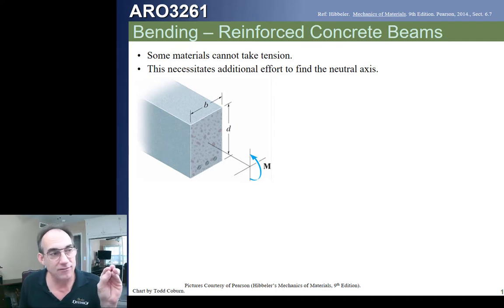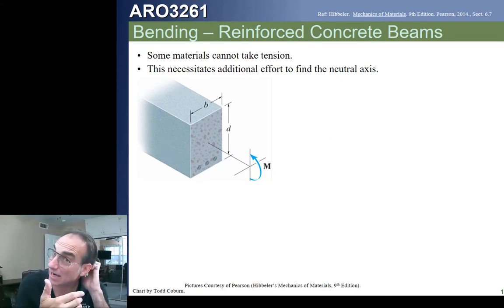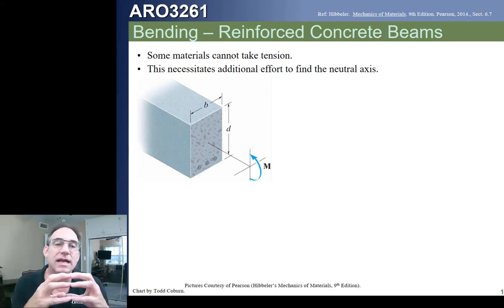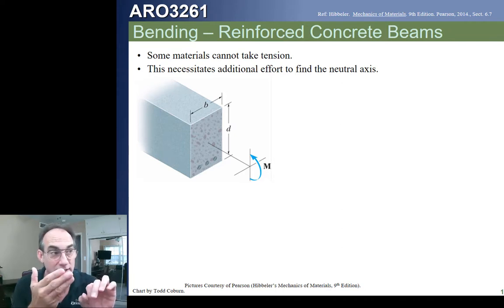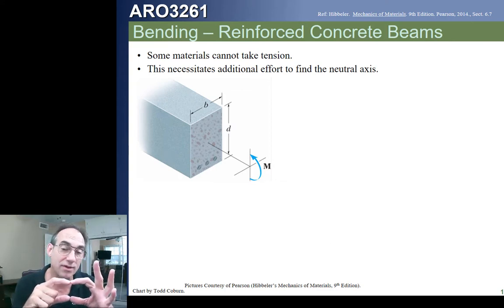If we have a reinforced concrete beam or any structure like that, what happens is the concrete has such a low tension strength that it tends to crack out at a low stress level. What this means is if it cracks out, it's not effective. But it is still effective in compression. Even if you have low loads during the life of the concrete, it's liable to develop cracks, which means we can't count on it for tension, which means we're only going to account for the steel area for carrying tension. We're going to count the concrete that's in compression and only the concrete that's in compression.